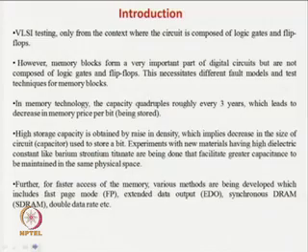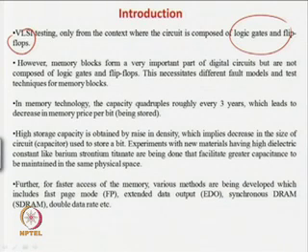In the case of memory testing, you have to observe that it will be quite different from the other digital testing of synchronous, asynchronous or combinational circuits. Why? Because all the digital circuits, sequential and combinational, whatever we discussed till now, were comprised of logic gates and flip-flops. Flip-flops are themselves comprised of logic gates. But the memory blocks actually work in a very different way.